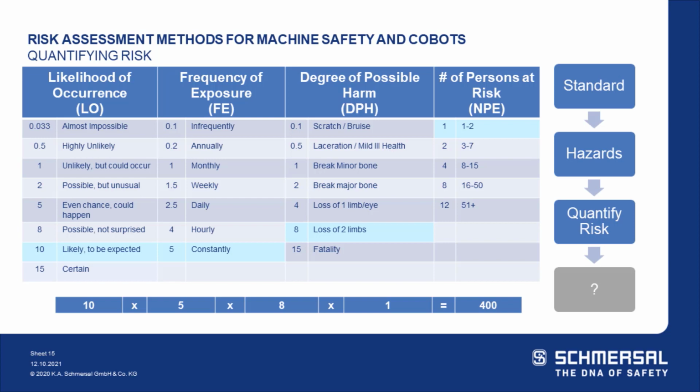Before we start this, every risk assessment, if you're doing an existing machine, now for machine builders this wouldn't be the case, but if you're doing an existing machine, and just like the story I told, it had light curtains, we want to remove those light curtains. We don't remove them physically, you're not taking them off, but in your mind, remove them. And this is why we're quantifying the risk without any safety on it. We have to see how dangerous it is, right? I'll explain it later, but we're removing those light curtains in our brain, and we'll do the risk that way. We'll do this together today, right?